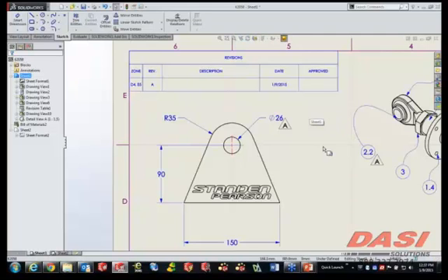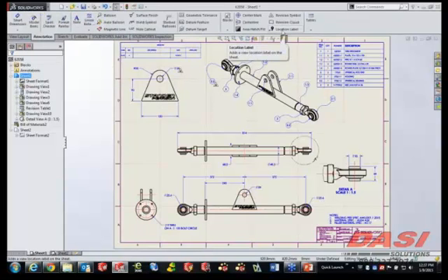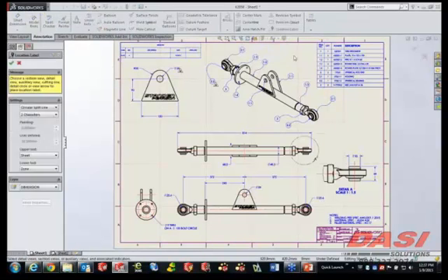These zones are usable for another area of the software. And this has to do really more with the relationship from a parent to a child view, especially when multiple sheets are involved. It's under the Annotations tab, and it's called a location label. Now, location labels cannot be inserted to a view that doesn't have a child. Some of these are front, top, and right views, and they'd have child views, but we're talking sections and details with this.